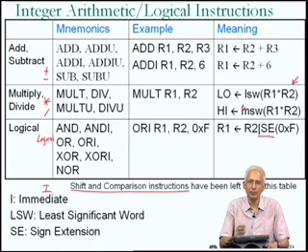In other words, the operation that we just saw that the load byte instruction does in the hardware. Sign extension is the idea that a value can be extended to more bits by just replicating the sign bit, or the most significant bit, for the remaining bits that have to be filled. So with these three additional pieces of notation, we can understand the contents of this table.